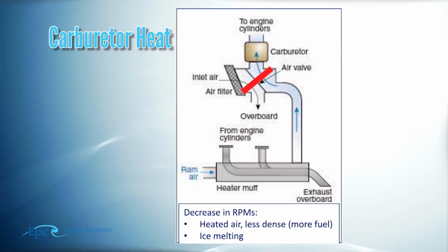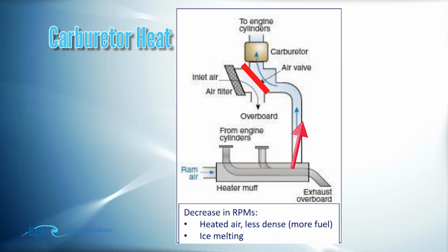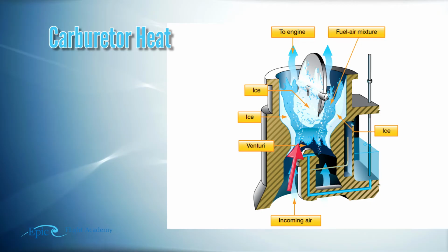When you do that, it'll be in the position you see here. Notice the intake air is going overboard, and air that was warmed by the muffler is now being directed into the carburetor, right up through this Venturi, melting that ice.